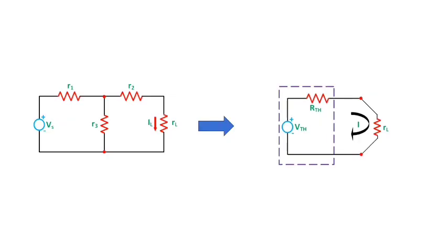So let us now try to understand what steps we are going to follow in order to verify Thevenin's theorem in our given DC network. Our Thevenin's theorem claims that whatever current is flowing here across resistance RL, which is your load resistance, will be the same in the case of Thevenin's equivalent circuit, which is somewhere here.